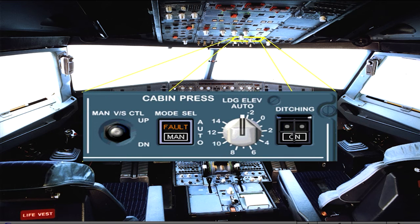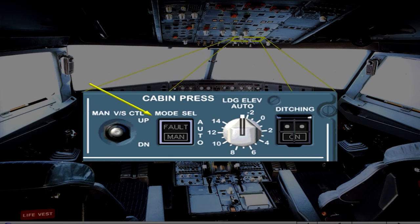The cabin pressure panel, on the overhead panel, contains controls to operate the pressurization system. Under normal conditions, no pilot action is required on this panel during flight. The pressurization mode select switch has two settings, automatic and manual. The normal position for this switch is lights out. In this position, the pressurization system is in automatic mode.